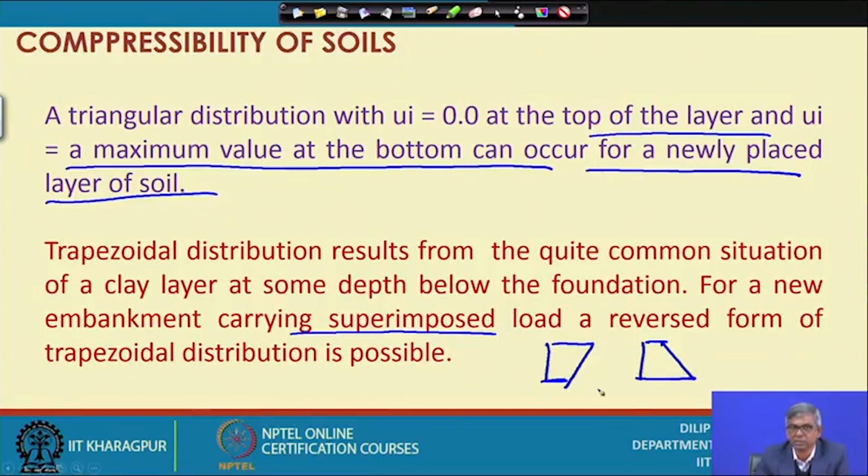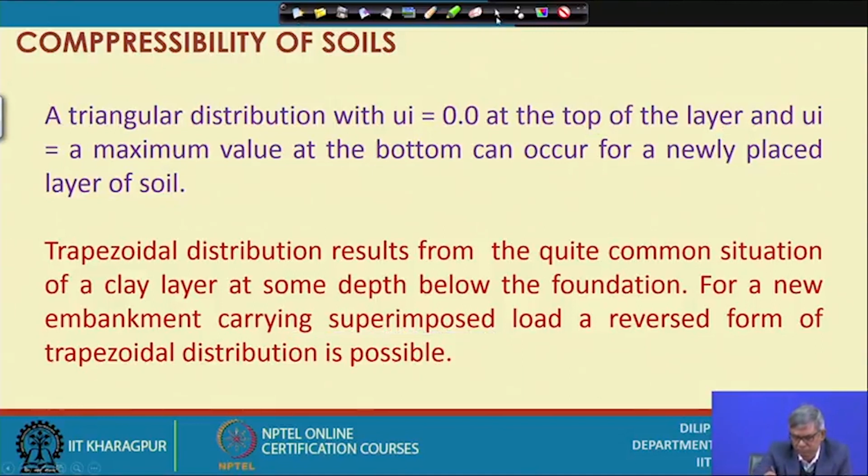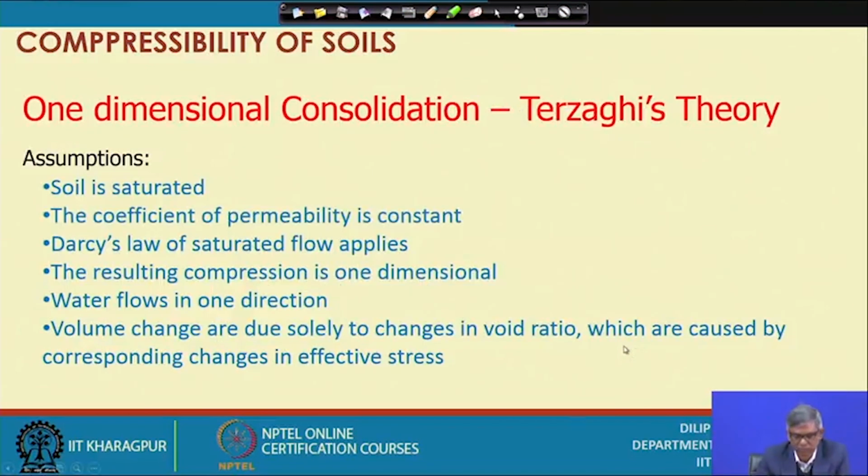This pore pressure distribution, whatever we could visualize, will be useful to analyze later on. Now, the consolidation settlement theory was first developed by Terzaghi, which is the one dimensional consolidation theory. Later on a 3 dimensional consolidation theory was also developed, but right now we will concentrate on the one dimensional consolidation theory